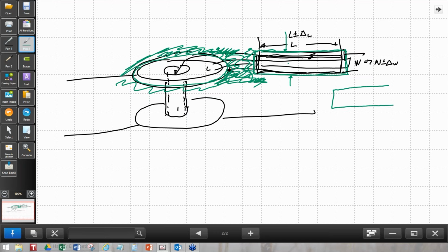So if the solder mask opening were to shift with respect to the hole, as long as it is open, you will not have any problem putting the lead of a part onto it and soldering it.